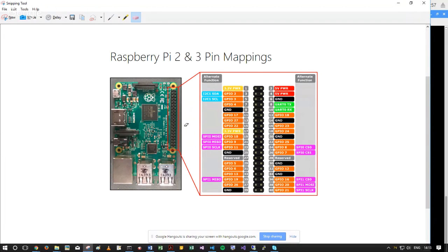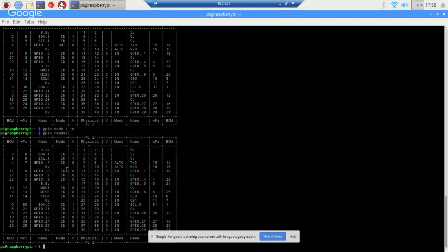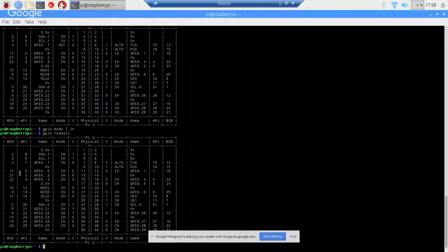So any circuit, you can see which 2 pins it's connected to. It's pin 7, GPIO 4, and ground, right? So remember we need a high, and the circuit has to be connected back to the ground. So we want to output a 1 on the GPIO wire, Pi pin 7. So to do that,